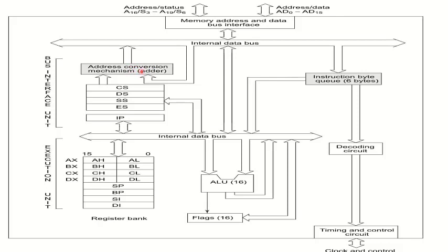As we know, the 8086 microprocessor has a 20-bit address line, so the maximum memory will be 1 MB, or 2 to the power 20. It means there will be 20 address lines, and the physical address will be 20 bits.